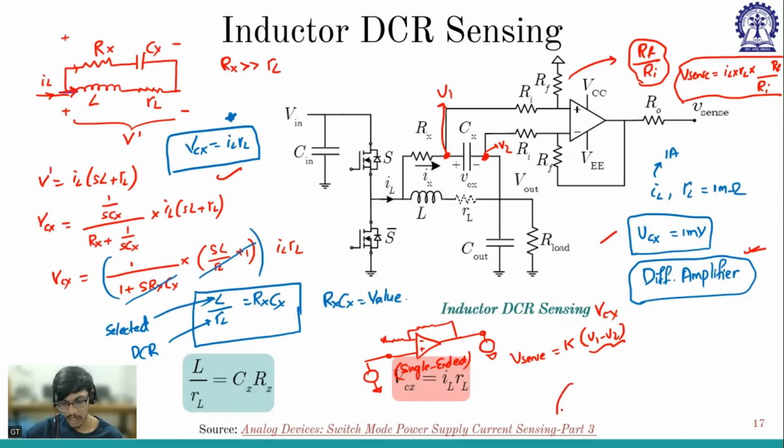So there is this datasheet which we can go through to get the details. Yes. Hello. Yes. DCR stands for? Sorry, DCR stands for DC resistance, direct current resistance. So it is in series with L, and here we have ESR, equivalent series resistance.